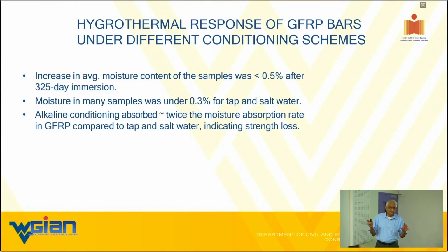Vinyl esters are approximately what? 2.5 times more expensive than polyesters. I don't know how much more here in this country. In our country, it's about $1.80 or so per pound for vinyl ester, 75 cents or so for polyester, maybe 80 cents. So, but that's what we did. So the message is, if you think vinyl ester is too expensive, use polyester.